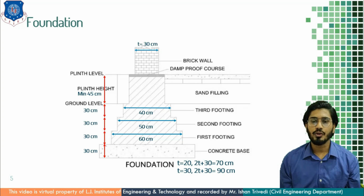For the entire footing from its concrete base to the third footing, the depth of each layer is 30 centimeter. Remember, the depth of each footing is 30 centimeter. If I sum all this brick masonry and concrete base, it will be 1.2 meter in total. This is the case of the outermost wall.